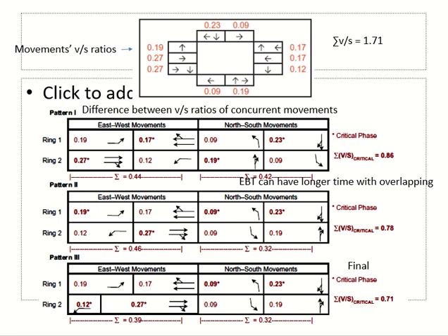So you made the first timing plan. Obviously, the demand will change, right? Every intersection will have its own demand, own lane width, and own saturation flow rate. So, for example, you did it for another intersection. When you made the first phasing plan, even after doing the combination and merging, you are getting a V by S ratio of 0.9, 0.95. This will be very difficult to design. So the V by S ratio should be as low as possible. The design will become better. That's why we discuss these things.